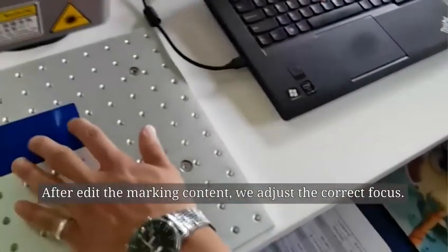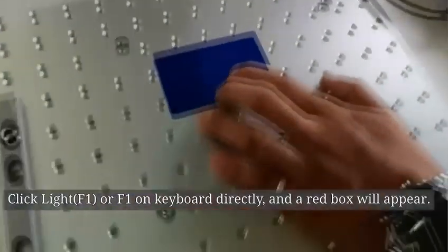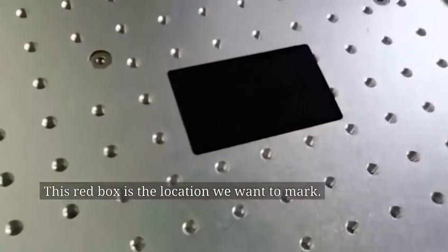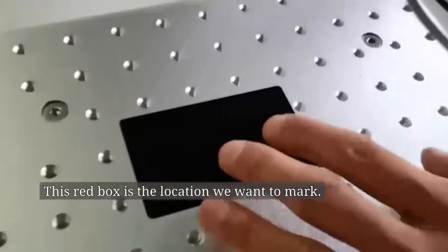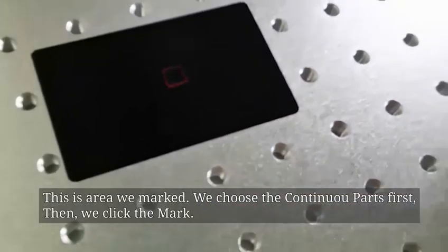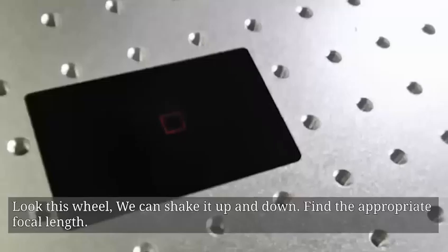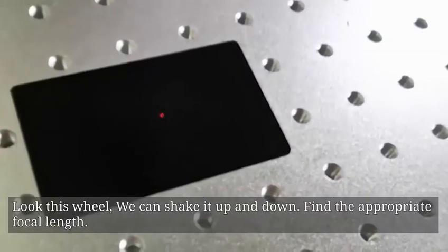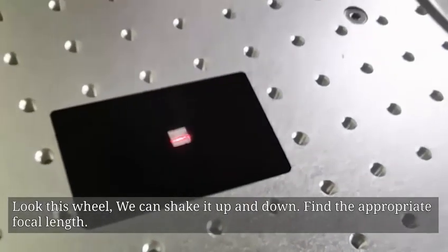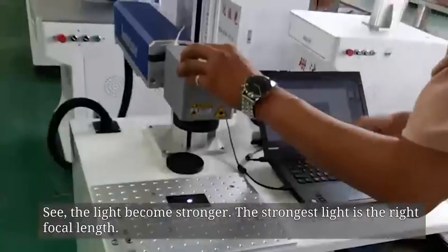The bigger the power and the lower the speed, the deeper the marking depth will be. After editing the marking content, we adjust the correct focal length. Click Light, F1, or F1 on the keyboard directly, and a red box will appear. This red box is the location we want to mark. This is the area we marked. We choose the continuous parts first, then we click Mark. Look, we can shake it up and down to find the appropriate focal length. See, the light becomes stronger. The strongest light is the right focal length.